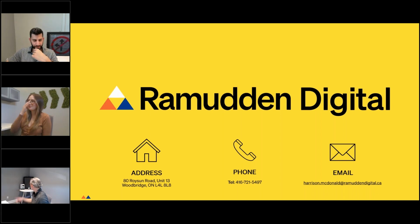You might see behind me, there's a super high resolution version of the same sign. The sign that Eric's been talking about today is a 10 millimeter pixel pitch, which means the space between the pixels is 10 millimeters. So when we have 64 by 64 pixels, it's 64 by 64 centimeters. And this sign here is a 3 millimeter pixel pitch. So we have a 3 times smaller pixel pitch, which means something like 10 times the number of pixels overall.